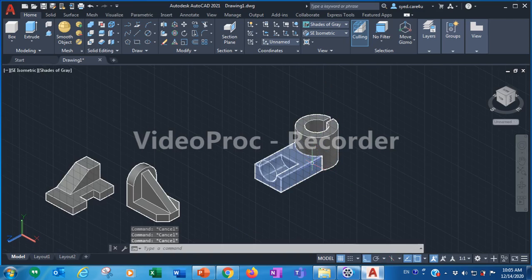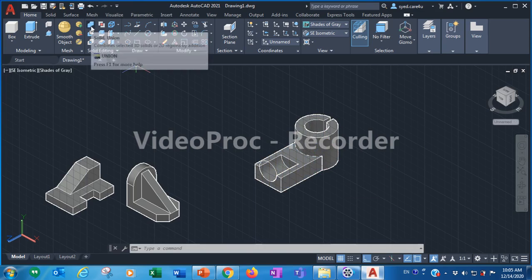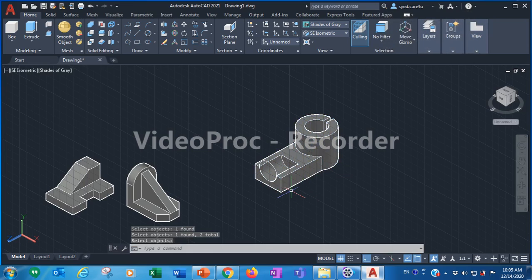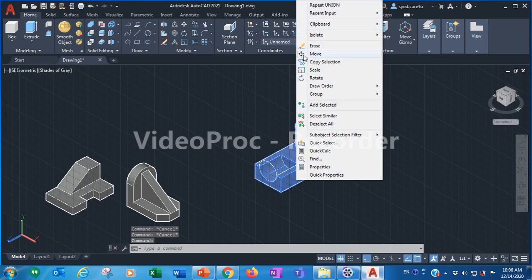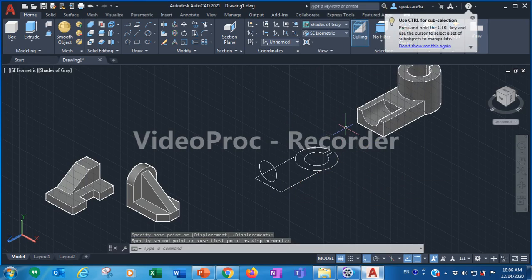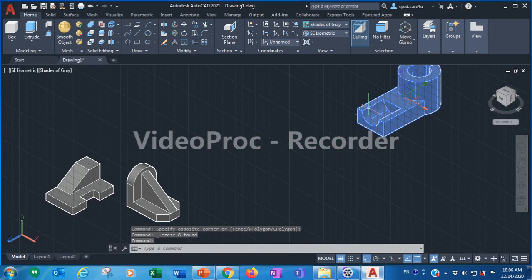So now these two parts are behaving like separate parts. In order to join them, click solid union, click on the first object, click on the second object, then press enter. Now these are behaving like a single object. So in order to delete the construction lines, click on the figure, right click, move the figure and delete the construction lines. So now again move it closely.